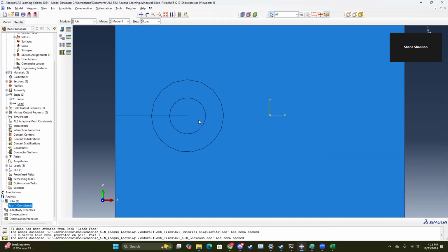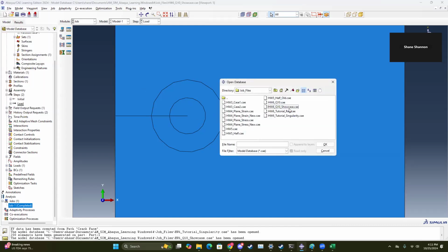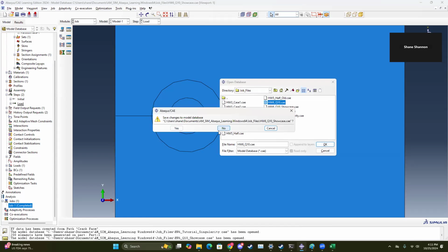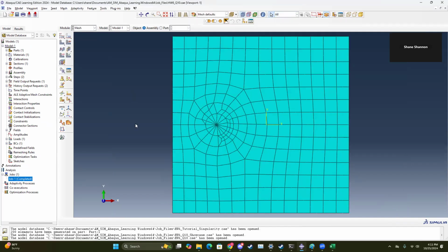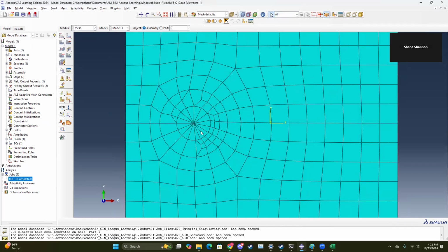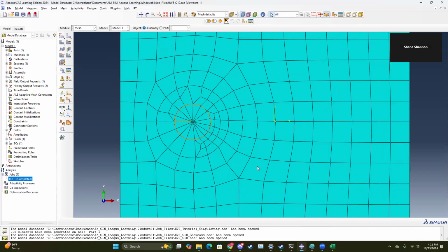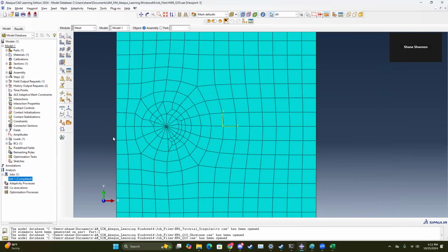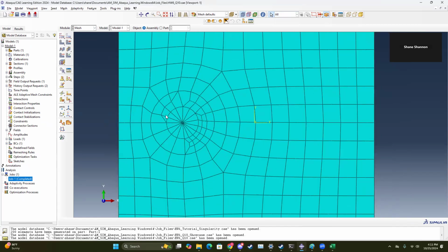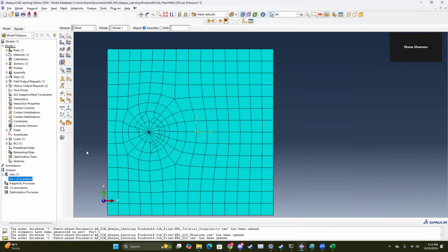Again, the main thing is that around the crack tip you want quad. Where's my mesh? Yeah, you see, this is how I was able to get it using the exact steps in Singularity. There's some cleanup stuff I have to do. Not 100% sure why it turns out this way, but this right here is the end goal for that question, what you want it to look like.